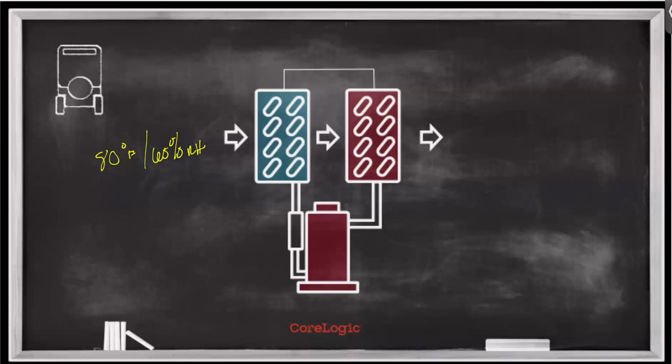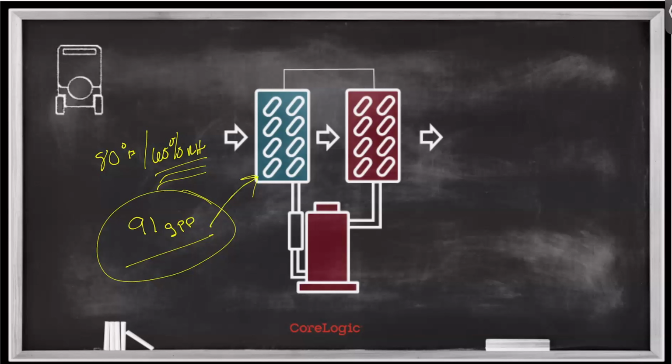the dehumidifier? Now, remember, when we look at humidity control, we don't use relative humidity. We have to pull out a psychrometric chart or our psychrometric calculator if we have one of those apps for our phone, and we'd have to convert this into grains per pound. That just happens to be about 91 grains per pound. And that's the unit of measure that we will use to understand how well the dehumidifier is operating. Now, this measurement by itself doesn't tell me anything. This is the air entering the dehumidifier. The next measurement I need is what's leaving the dehumidifier, right? That'll help me understand what the dehumidifier is doing.